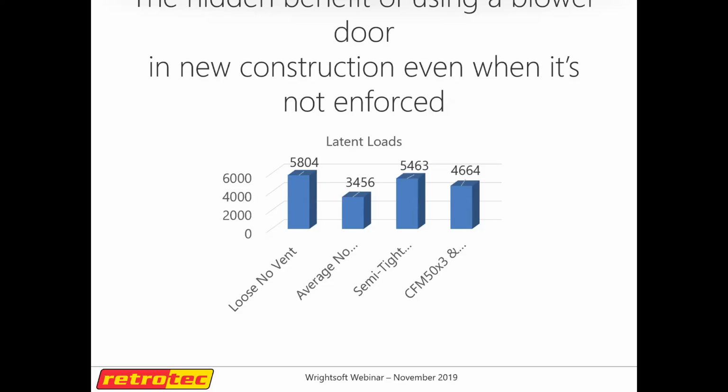But if you're in an area where they're enforcing those codes, the HVAC professional has to do a load calculation, and they have to design ventilation for the home that complies with ASHRAE 62. That's the enforceable standard in new construction. The rules in the ResNet standard that you use with the BPI recommendations are great for retrofit. But there's a really specific standard that you have to comply with for the IECC code, and that's ASHRAE 62.